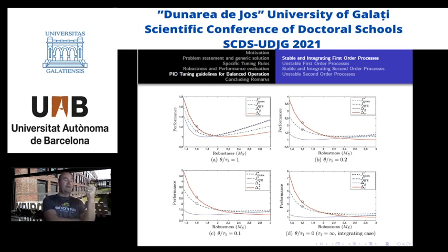The case of 0 is where the time constant is infinite and you go to the integrating case. Of course, you can get many more cases in the middle. This is just to show you, but if you take smaller, shorter steps, you get a better representation of the plant family. So what changes in each of the pictures is that the slope keeps changing.